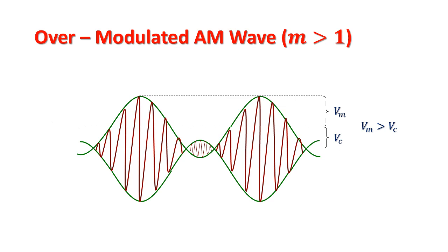Broadcast stations using amplitude modulation take measures to ensure that the carriers or signals for their transmissions never become overmodulated. The transmitters incorporate limiters to prevent more than 100% modulation. They also normally incorporate automatic audio gain controls to keep the audio levels such that near 100% modulation levels are achieved for most of the time. In this way, the signal sounds clearer and stronger when demodulated.